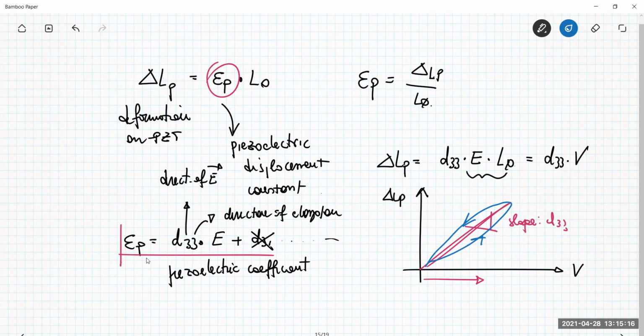What about the electric field that you are applying here? Of course, the electric field cannot be whatever value you have in mind. If you exceed a specific critical threshold of this electric field, the material experiences mechanical stresses that can lead to the destruction of the component, and you can no longer exploit the piezoelectric effect.